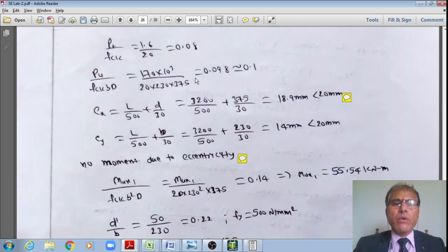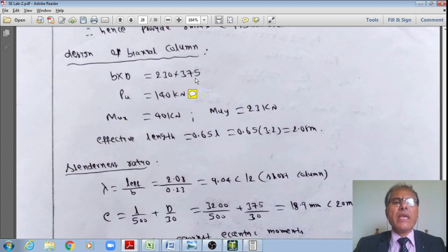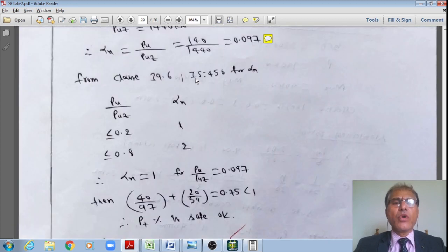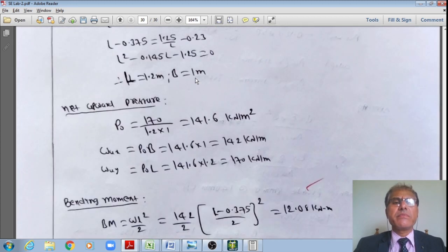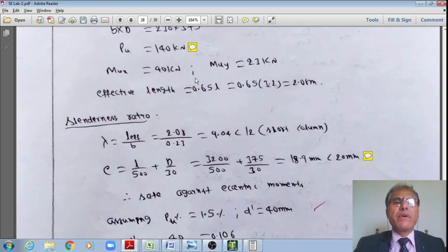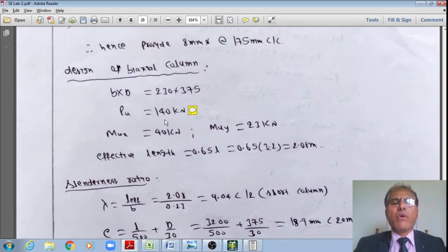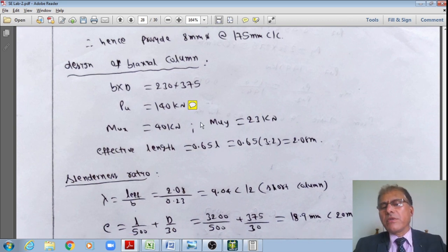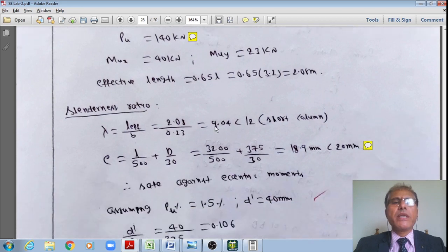Manual design is not applicable now, right? Even I have designed those end columns subjected to biaxial bending, right? They were subjected to this much of load, 140, 40, 23, but that is not the case. As per STAAD, I now have only some 53 and a 3-point minimum eccentricity, some 3.4 kilonewton meter only.